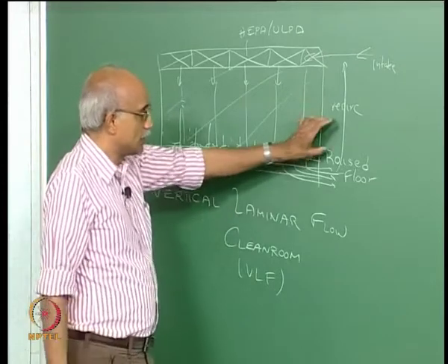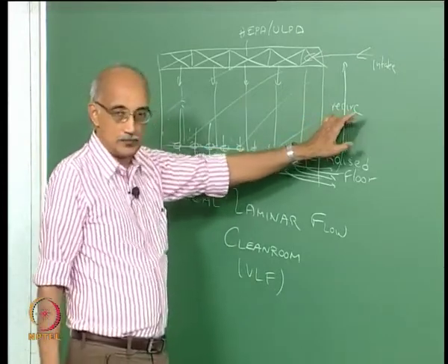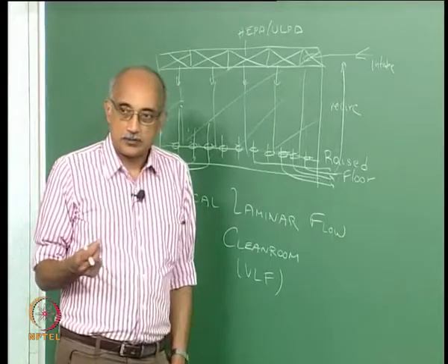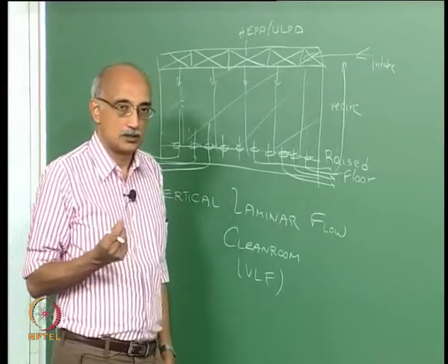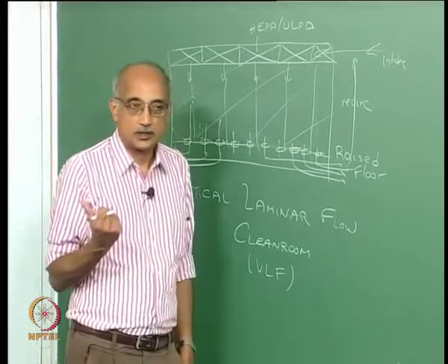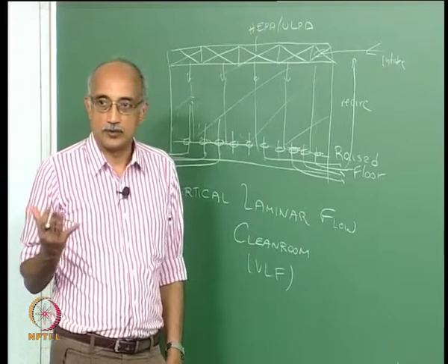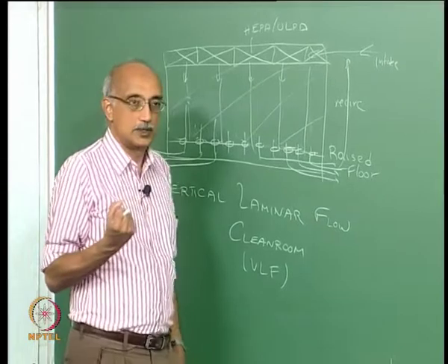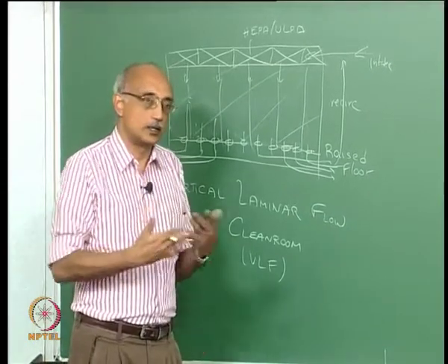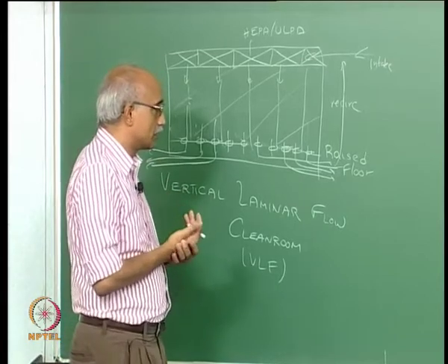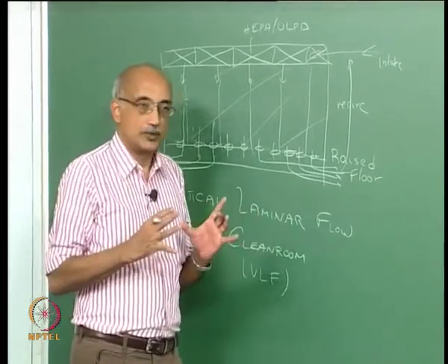So this ratio of recirculation volume to makeup volume, or intake volume of air, is a very critical parameter, and it needs to be optimized for every clean room application you have. So in order to do that, what do you do first? You have to develop a model for the clean room, right? So you have to do CFD modeling to obtain a predictive description of how the flow field in this environment will behave. If you look at this, it's a classical fluid dynamic problem.